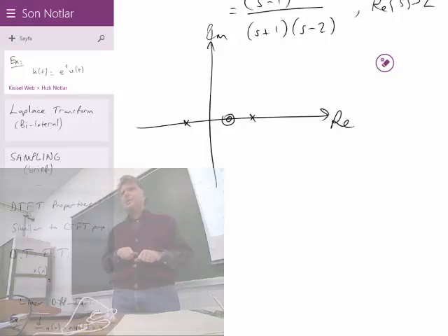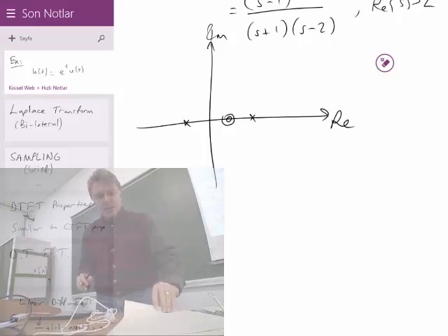Because sometimes poles and zeros cancel each other. That's how you eliminate a pole and make a system stable, for example. The way to stabilize the system is by eliminating a pole. For example, at s equal to 2 there is a pole, which is a problem. Then how do you stabilize the system? By inserting a zero at s equal to 2. The zero in the numerator will cancel the pole in the denominator. They will just cancel each other in the polynomials, so the pole will be gone and your system may become stable afterwards. So their cancellation is an important issue.